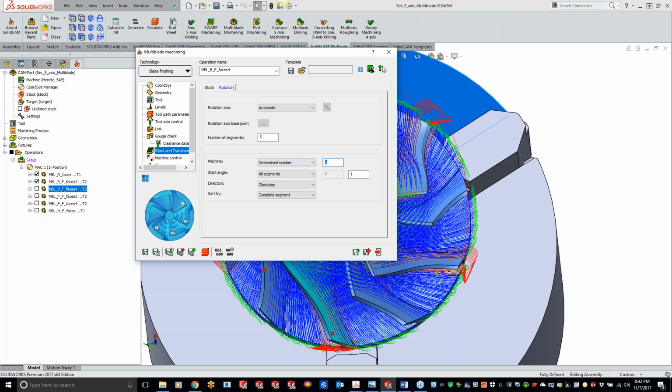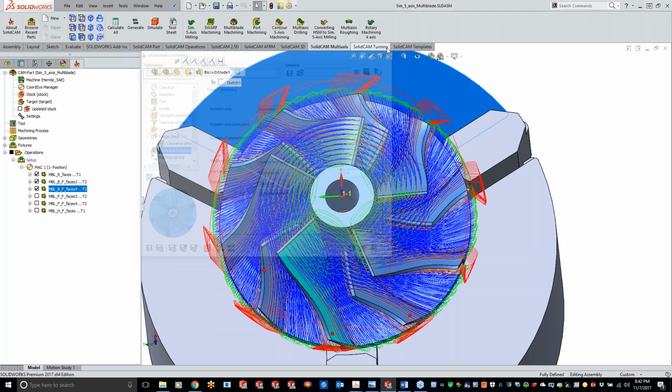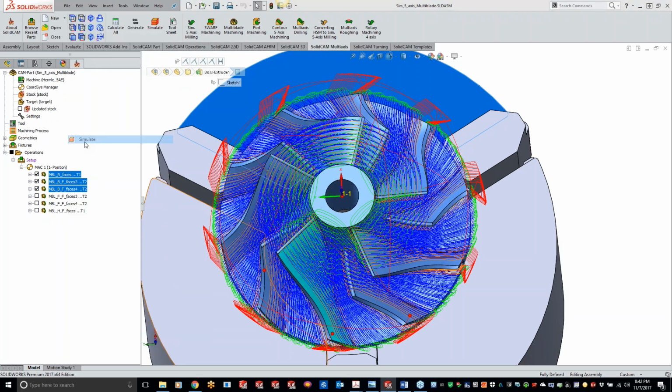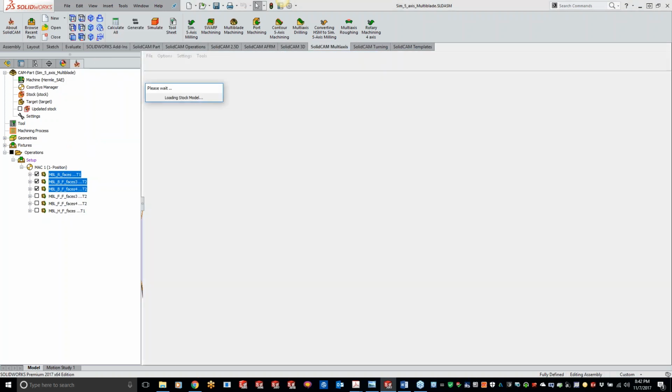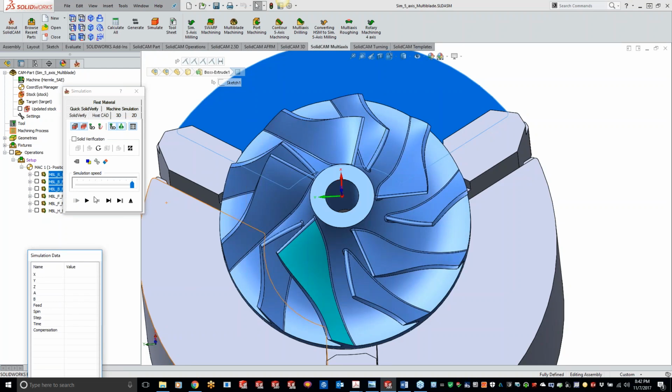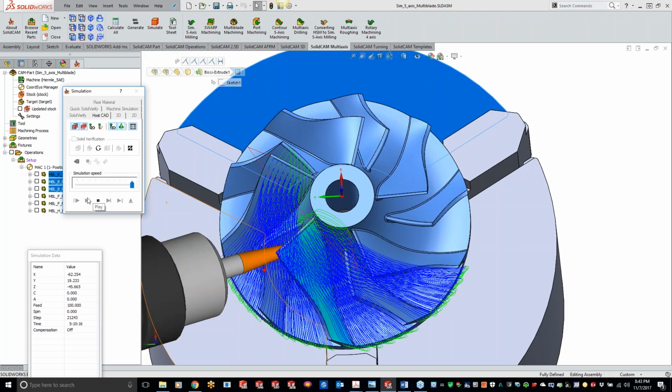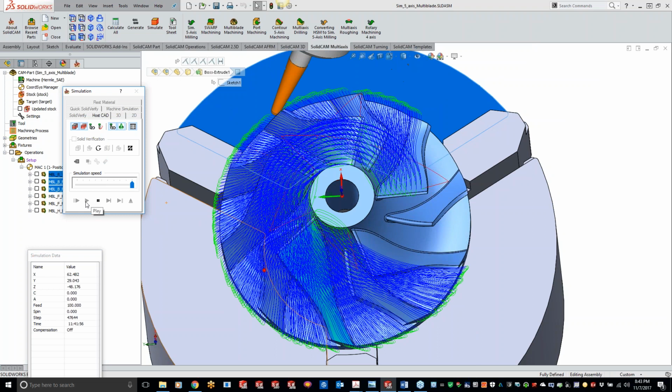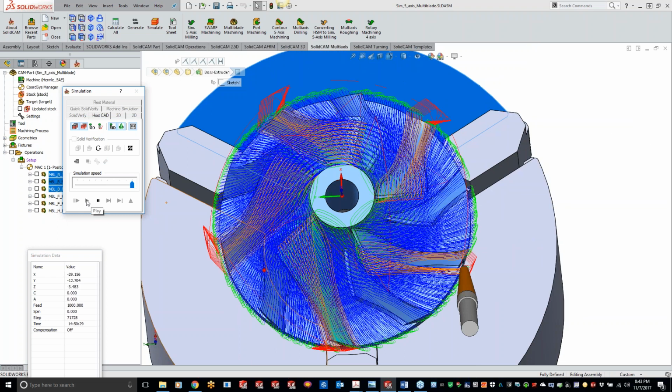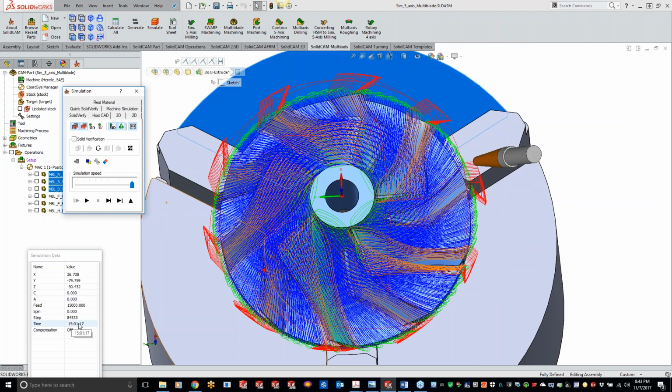So, and if you want, Ben, what I can do here is, since we have these first 3 operations, if we just do a simulate, and we can just do a host CAD right here. Now I haven't set any feed rates for those tools, so you can see our time is right here. So 15 hours, 1 minute and 17 seconds is the total time, but those feeds are probably my default feeds, and I didn't set any of those.